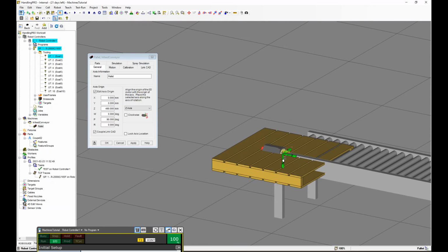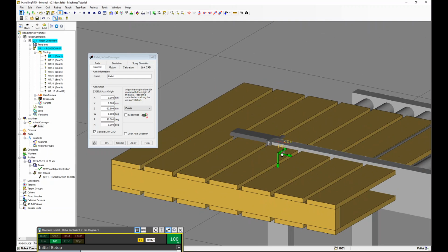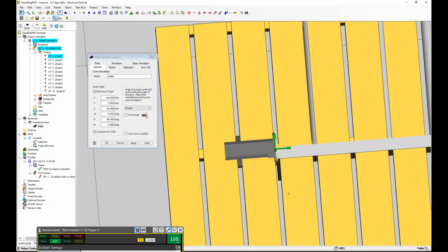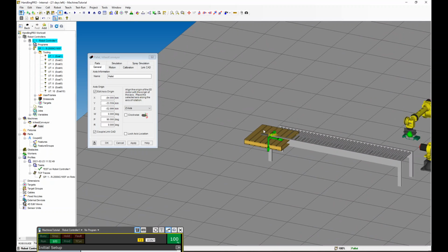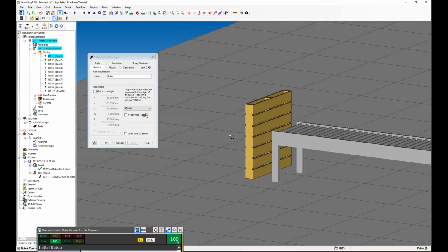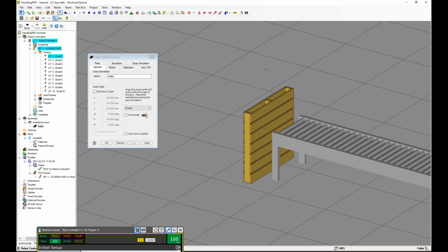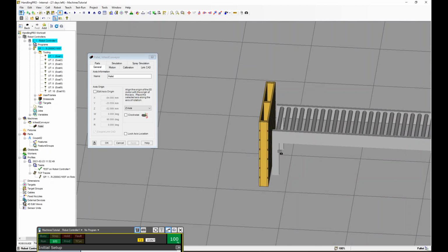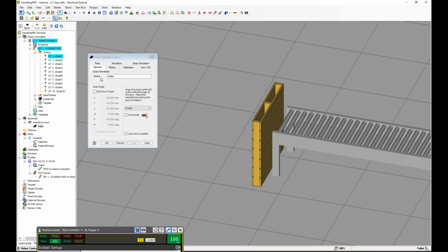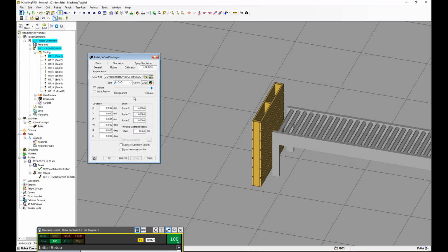And I'm going to just kind of halfway hide this motor back here, almost like it's bolted to the back of my conveyor. No one will ever really care, but now I have this axis origin with a Z axis pointing toward my robot at the origin here. That's going to be important in a minute. See when I click apply? When I click apply, it now wants to move my link in that Z axis. I could have left my motor hanging up vertically in space and said X axis, but I'd rather have it be this way, and then go to my link CAD tab.